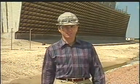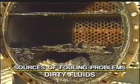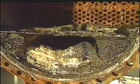A low-velocity flow can start the buildup of deposits on internal surfaces. These deposits can cause changes in temperature and pressure. The deposits have several sources. Process fluids may contain solid sediments. Once they settle, a restriction to the flow develops, and the restriction then causes more settling.